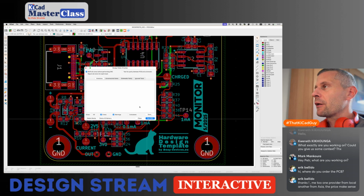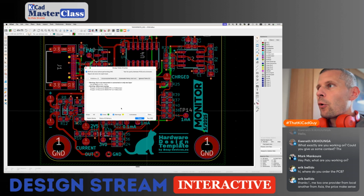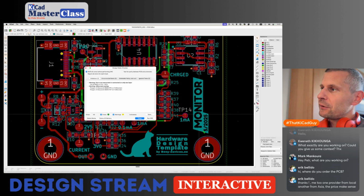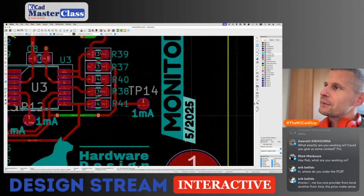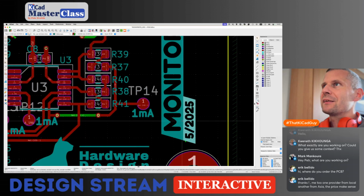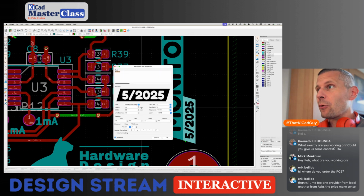So the design rules checker shows 2 warnings. One is the overlapped silk screen, because I usually place the name of the board and the date of the PCB layout creation near the name of the board.